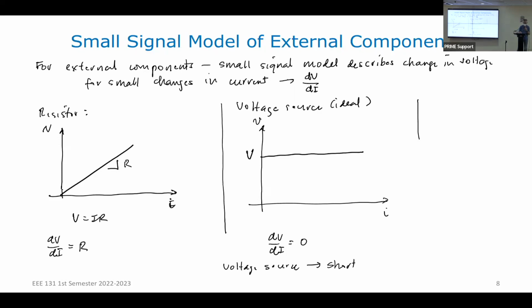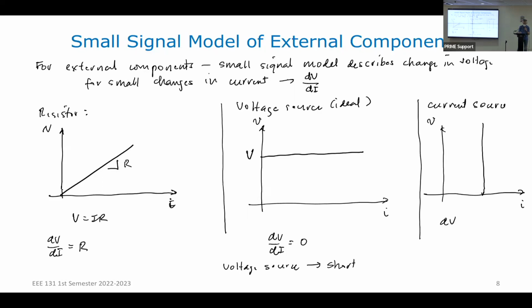And if you have a current source, if this is my voltage, this is my current. My current source looks like this. What is dV/dI? Wake up. Infinity. So my current source is an open circuit.